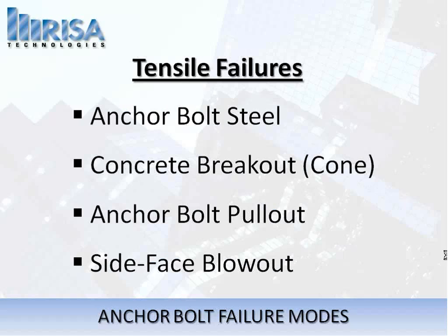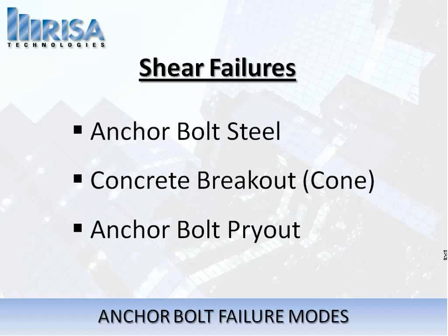Now, concrete breakout in terms of cone failure is another tensile failure. Anchor bolt pullout is another one, and side face blowout is another one, although typically the first two are going to govern. Now, there's 3 shear failure modes.